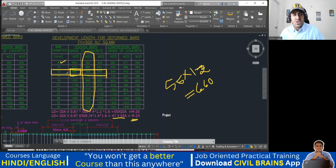The same problem is happening here also. If it is a 12 diameter bar and I'm taking M25 grade of concrete, what will be my formula? 47 times the diameter. So 47 into 12, I'm getting 564 with this formula. But here the answer is 583. Roughly 20 mm excess they are getting. I don't know how they are getting roughly 20 mm excess, because even this is not matching.